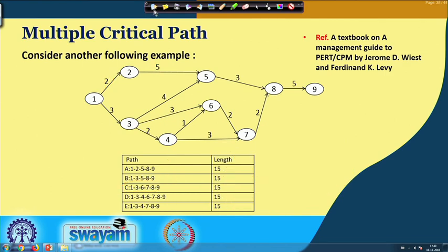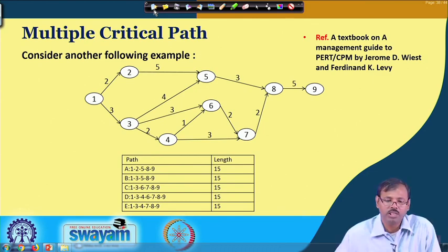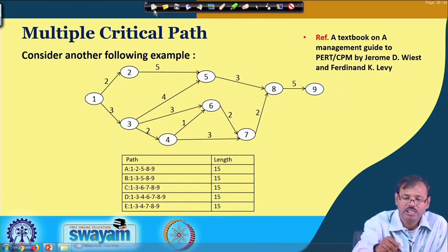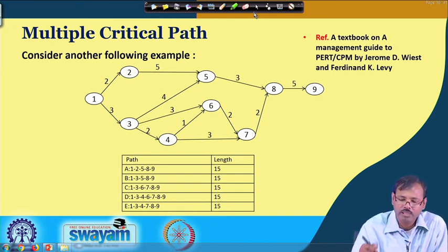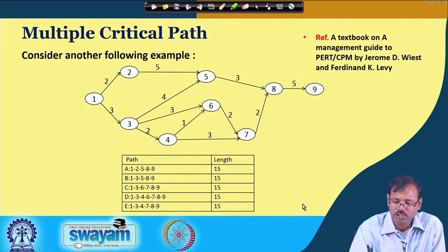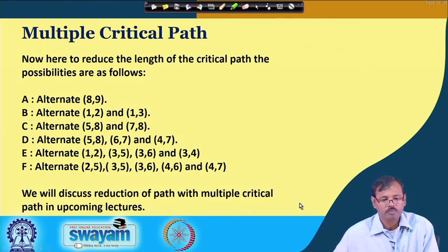Then with the analysis of the critical path, we are able to come out with the decision in which we need additional manpower, man machines, and in which we can withdraw some man machines, excess manpower provided. So, some length may be extended, some length may be shortened to achieve the target date and to achieve the required costing in these networks.